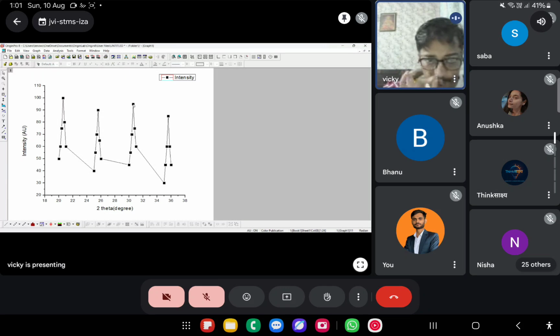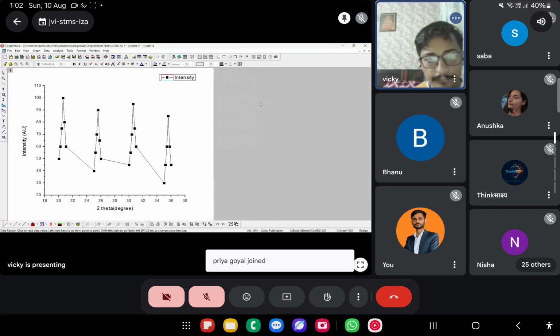Now label it. Suppose you want to analyze a particular data point and see how it comes out. You can select the data reader in the toolbar on the very left side. We have different options: zoom in, screen reader, data reader, data selector, and so on. If you put your cursor on a particular point and click it, it shows your x and y. So the x-axis is 25.6 and the y-axis is basically 90, right? This is basically your one-off analysis.